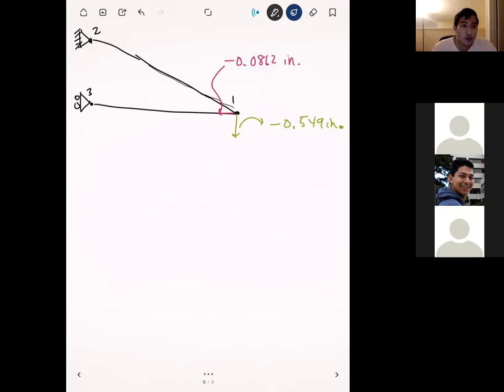In that case, the car is resting on the road, and after it collides with the wall, we don't want the car to crumple into the ground. So we want to simulate the fact that the ground is there. The car hits the wall, bounces off, and goes up. That's a case where you would want to constrain only in one direction, because if we completely fix the car, then it wouldn't hit the wall. We only want to prevent the car from clipping into the ground. So that's one situation where you would want a roller. You can think of it as part of your toolbox for helping you simulate realistic situations.